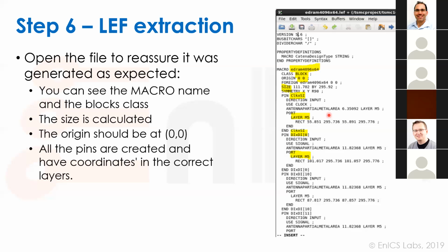So it's really easy to not cause antennas, but if you're not aware of it, they will be caused because you're making all these routes and you don't care about any type of thing like this. And if you don't check it, it's going to be caused. So inside the LEFs, you just lose the information there. And so you're routing at a higher level, you're connecting to these blocks, and you're causing these violations by mistake because you don't know that there's a problem underneath.